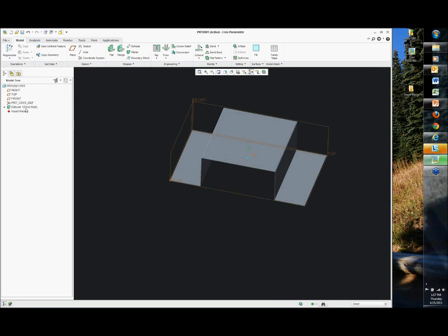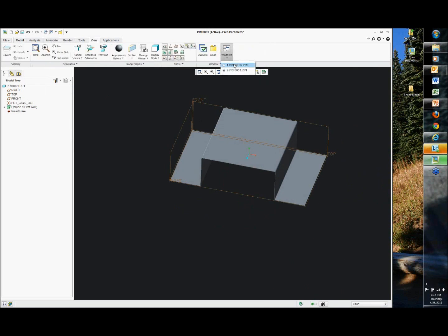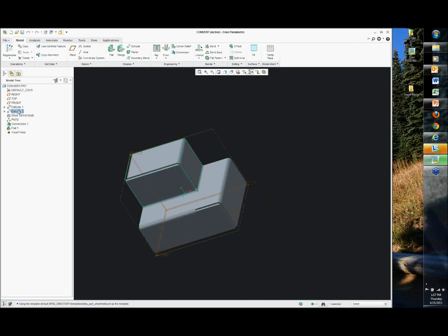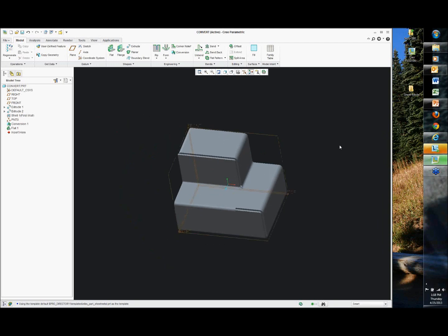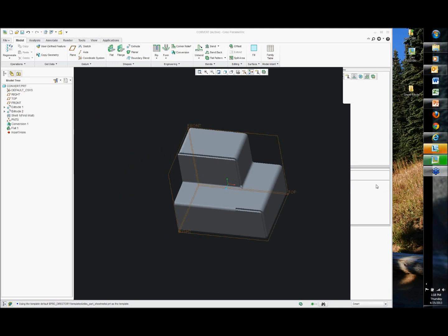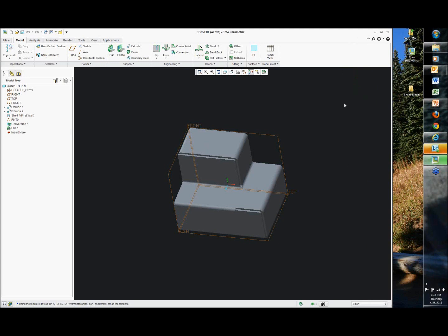And this was starting in sheet metal. So if we just look simply at the model trees, you can tell that this one wasn't started as a solid because they started with 2 extrudes and then the shell is the first wall. So that was the original question, the poll question. I did not see the answers of the poll. I'm not sure if I can get to them here, just to see how many people were doing it one way or the other. It really doesn't matter so much which way you go. It's more that you understand that there are 2 ways, and you could do either one. And sometimes it's easier to build a solid shape and try to convert it to sheet metal. Sometimes it's better to make a sheet metal part and just work from that.